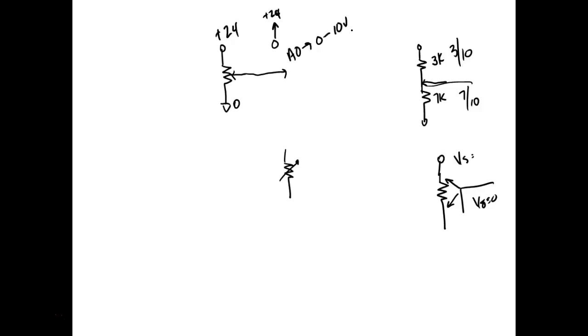That makes sense? Y'all follow me so far? So that means on an Allen Bradley 1100 PLC, if I only bring in a 5-volt analog input, then I'm losing half my counts. Instead of getting 1024, I'm only getting 511, right? Does that make sense? Okay. So I wouldn't have as good a resolution on 5 volts as I do on 10 volts.